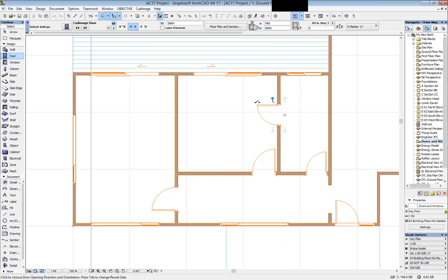Now of course I can choose the other side, the opposite side to the sun icon, but if I go to my CADimage door and window schedule, that door will now open away from me, therefore the doors that show up on site will probably be hung the wrong way. So that's all we need to do. Click into the room that you're concerned about and then choose whether you are left hung or right hung. Actually, I'll get rid of those doors because that'll confuse later.